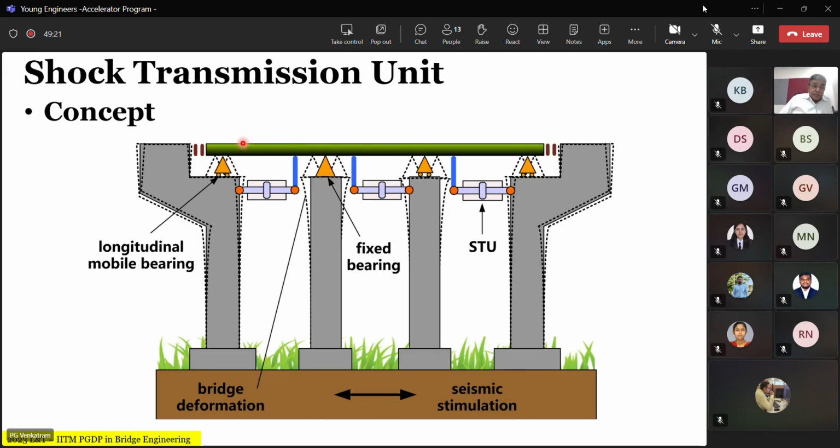Okay. The reason why this is done like that, in almost all the bridges in the transverse direction, is that you always have one hinge in a pair of bearings. Every bridge deck will have at least 2 bearings. Generally, there are certain situations where you may have 1 bearing, but at least 2 bearings in the transverse direction. So one of them is locking and the other one is rolling in the perpendicular direction. So therefore, you don't end up providing the shock transmission.